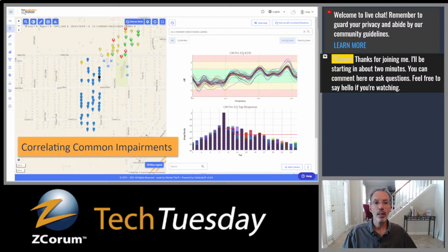And you'll notice here, you've got this yellow modem in the midst of all these blue modems, and sometimes you'll see this. You might see a yellow modem here, a red modem there, surrounded by some blue modems. And usually what that means is that this particular device, maybe it's got such a bad in-home problem or some other issue, that its in-channel frequency response is different enough that the application just says, well, I can't really correlate this one because it's different enough.